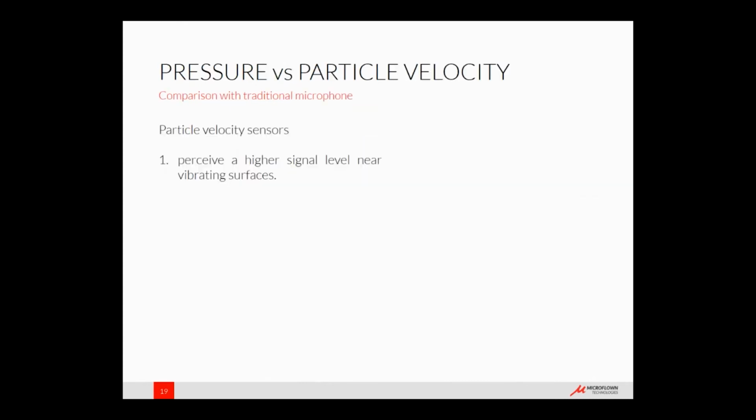There's some significant difference between pressure and particle velocity. So we're going to talk a bit about that and why it is interesting to use particle velocity as an alternative for sound pressure. I already quickly mentioned the two things, the directivity and the near field effect. We start with the near field effect, which is related to when you measure with the sensor relatively close to the source or the structure of interest that you want to measure.